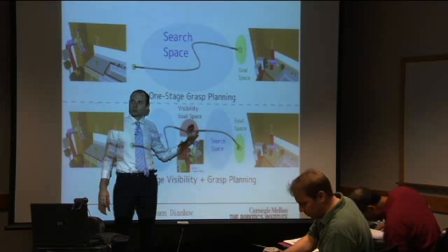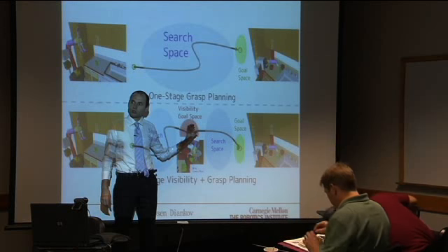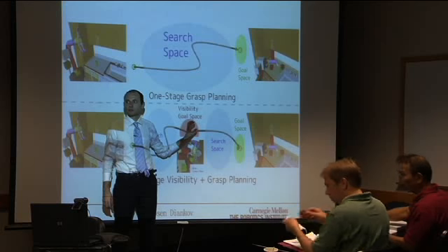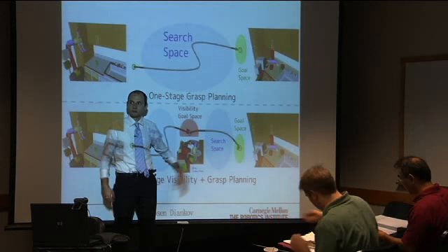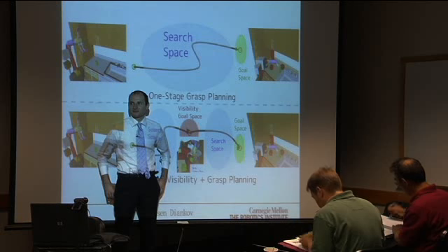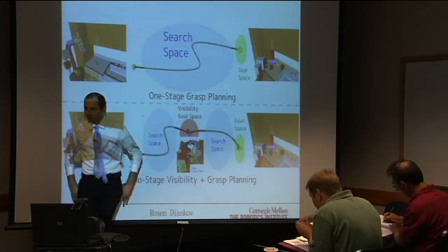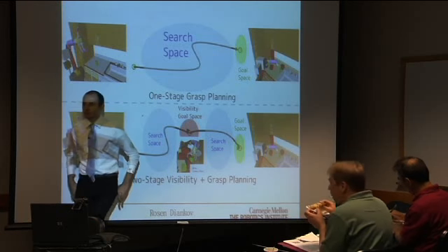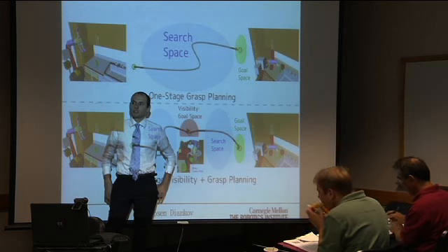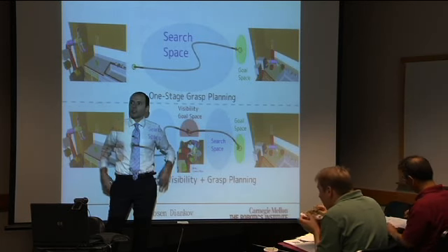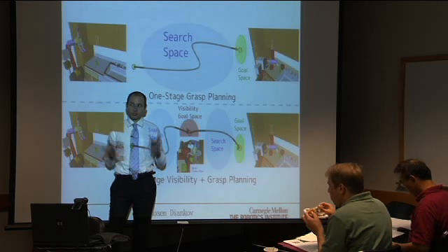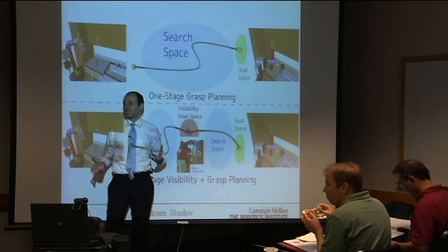When you say visual servoing, I see you're definitely talking about the gripping and the actual grasp part. But coming from my side, where we did a lot of ground robots without arms on them, visual servoing meant anything where you have a sensor and you're aiming it and it's feeding into the control system. So in the first part, you're visually servoing to the object because you're planning to it. If you're tracking an object and you need to react very fast to the object's behavior, then you would definitely need this. You cannot not need it.